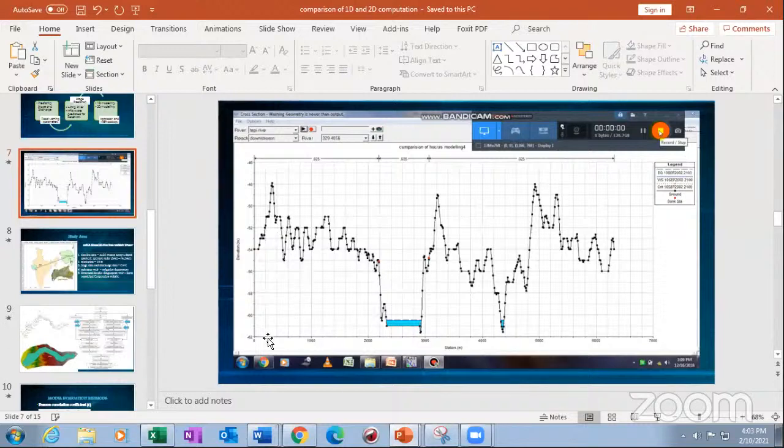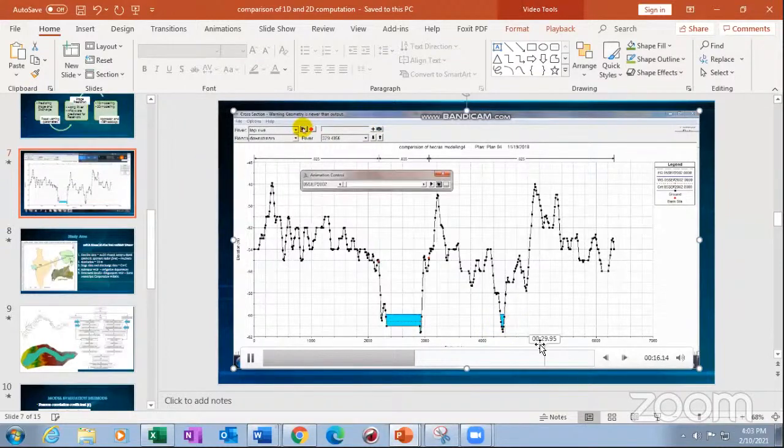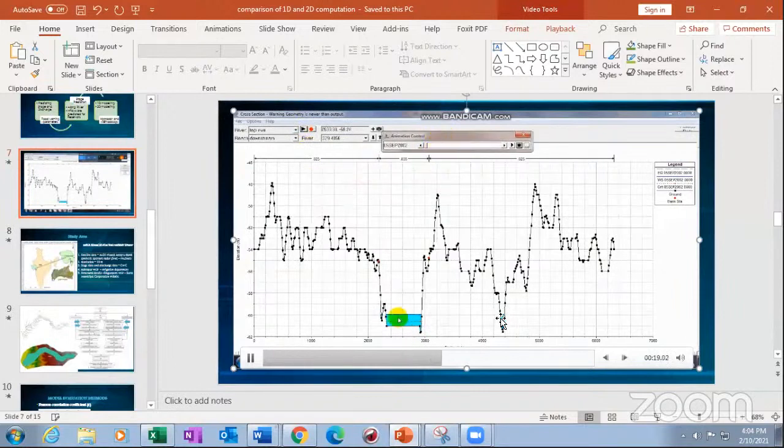I'll show you with this video. Can you see here the level? This level and this level. The problem is this level, because this is the actual channel from where the water has been released. But you see water is increasing in level here because this small tributary's cross-section is at the same level as the main channel. So what is getting accumulated in this also? This is the problem with the HEC-RAS 1D model.